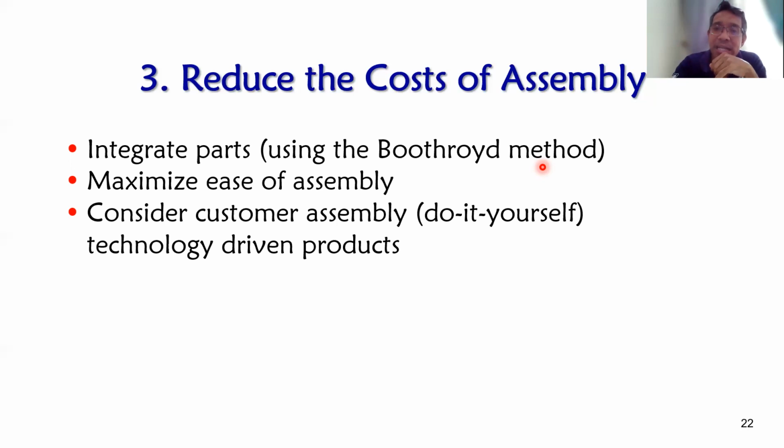Integrated parts also allow the relation among critical geometric features. So when you use an integrated part, they already think about critical geometries. You don't need to machine to produce that, because in a single process you can produce the geometric features to be controlled by the part.